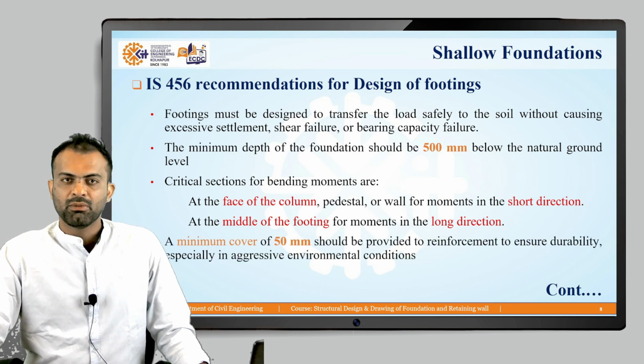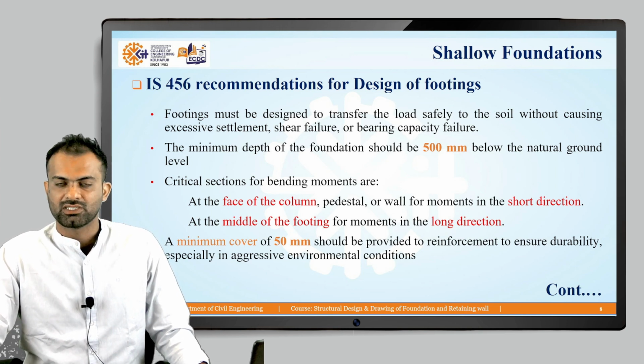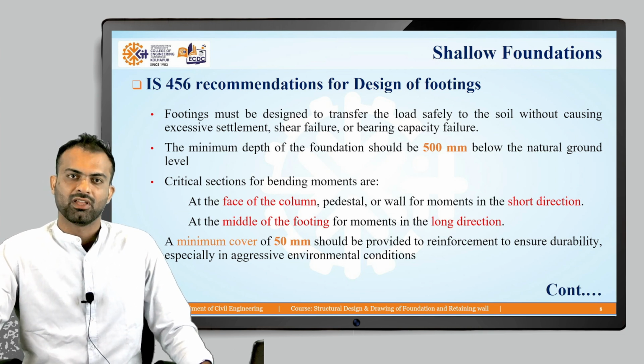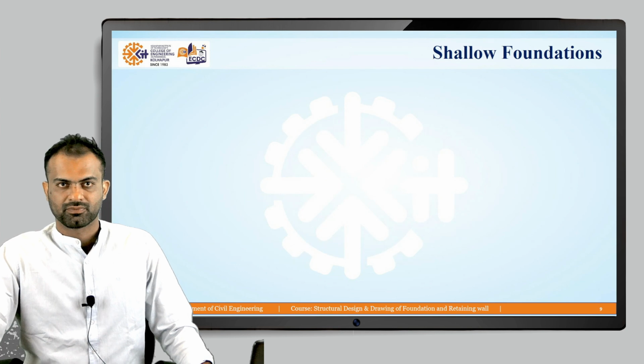So the minimum cover for the foundation is 50 mm, so that we can ensure the durability of the foundation, because the soil has different alkalis and acids. So to protect the reinforcement in the foundation, we have to provide the minimum cover of 50 mm.